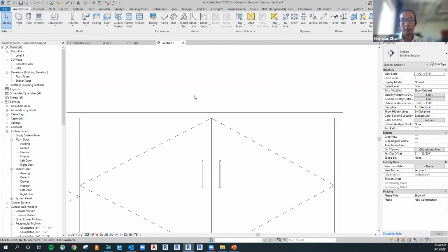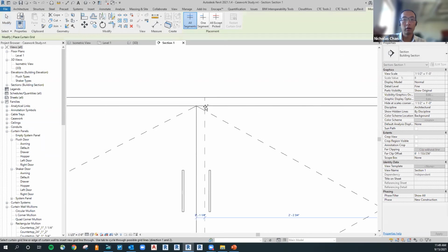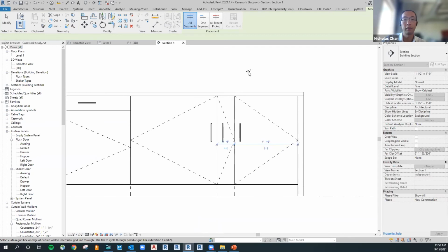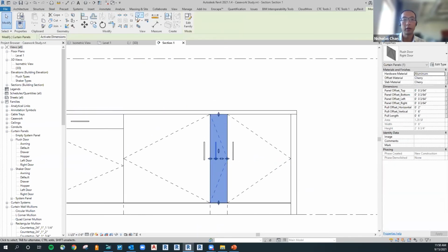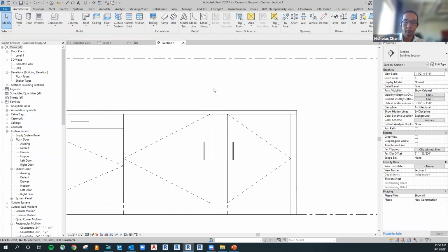You can basically create another grid line and then offset that, and then have a mullion in the back or a filled panel. This can be done a couple of different ways, I guess. You can use mullions, or you could actually do a filled panel. However, the filled panel might be flush with adjacent panels, but we can adjust the depth of these panels to allow for that to be realistically shown in the rendering.